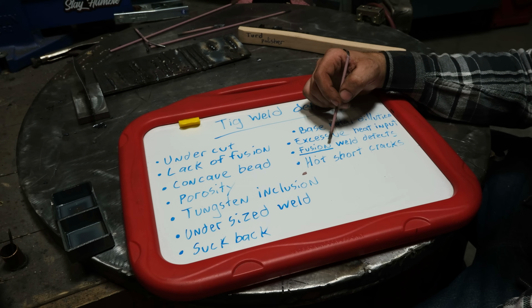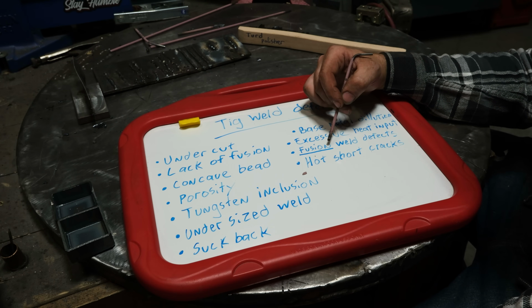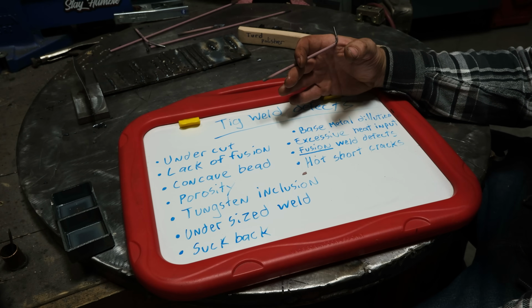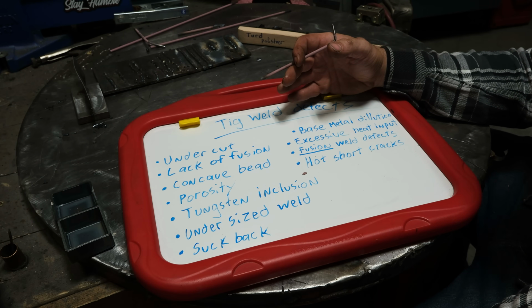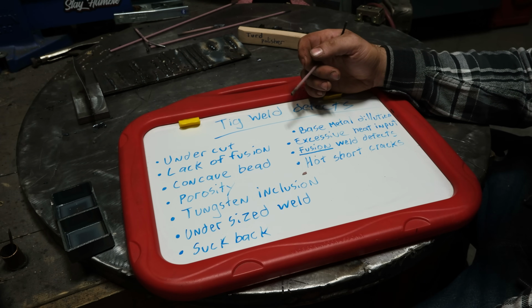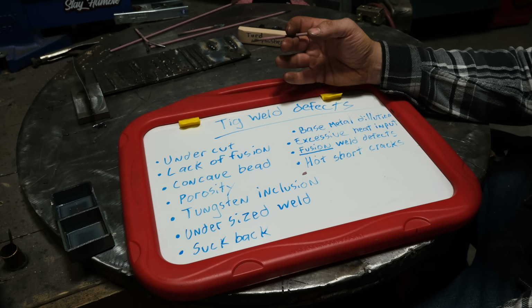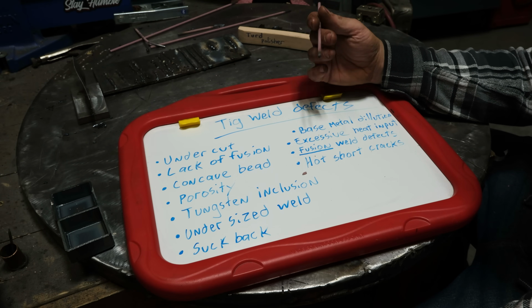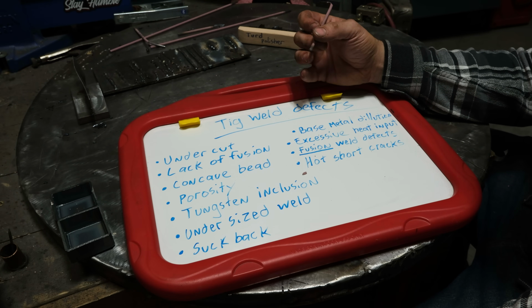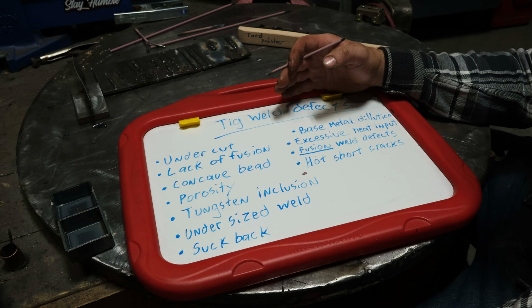an argon purge on the back side of something, like say you're welding stainless headers and you're going to fusion weld them, right? What will happen if you don't have an internal purge on that tube and you just basically lay a bead right over the top is it will pull oxidization from the inside of that tube all the way through to the face of it, and it's going to produce a weld that will likely crack when exposed to high heat, temperature cycles, and vibrations.